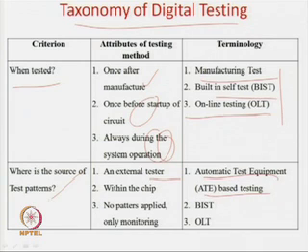Now, if I have manufactured a circuit and I put it in your laptop, obviously you cannot bring the ATE machine and test your circuit. So, in that case, the test pattern generator and the response analyzer are within your circuit. We will slowly see towards the end of the course how it is done. For equipment it is simple: you apply the patterns and observe the response. But if you put the whole ATE in miniature version in the circuit, then the test patterns can be applied from the circuit and also analyzed in the circuit itself. So, if the patterns are applied within the chip, it is the case of a BIST.